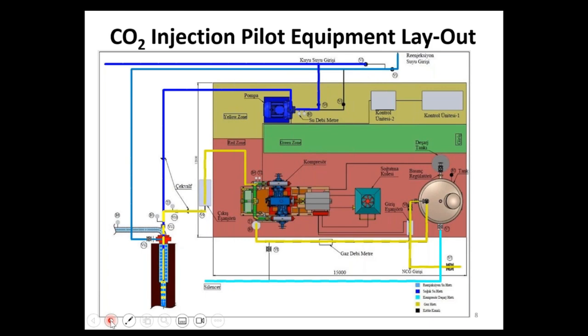When you go through the condenser in the power plant, you segregate: you condense down your brine and you release your NCG to the atmosphere. Your NCG is a gas. It's not a supercritical state or any fluid. Then, in order to re-inject it, you are going to inject a gas into a hot water, a fluid, which makes it a little bit challenging and difficult.